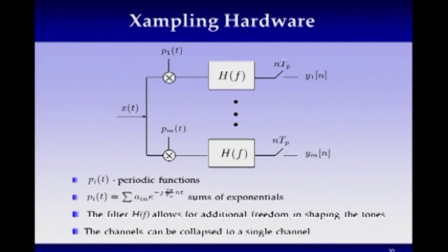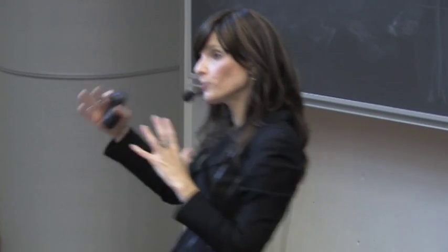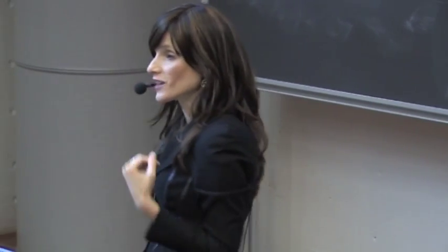But the nice thing is that now we could exploit mathematics again to help us. The nice mathematics is that if you take any signal that's periodic, then you could write it in terms of a Fourier sum, which means that a periodic signal actually has infinitely many sinusoids in it for free. So now, instead of multiplying with many, many sinusoids, all I have to do is multiply with one periodic function, and it's as if I'm multiplying with many, many sinusoids. This already allows us to do something very practical.